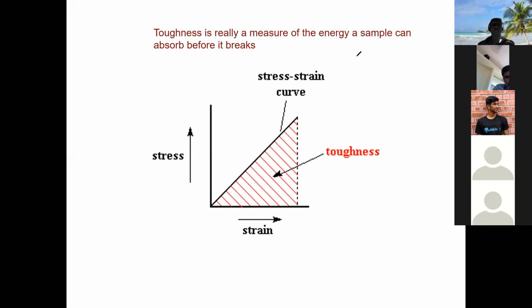So another property is the modulus of elasticity. If you look at it, the modulus of elasticity can be obtained from the slope, basically. If the slopes vary, then your modulus of elasticity value changes, right? And the area under this curve, that is, the stress strain curve, is your toughness. The area under the stress strain curve is your toughness, basically.